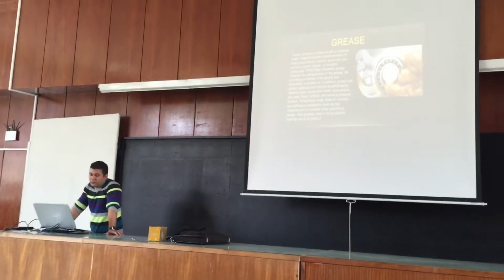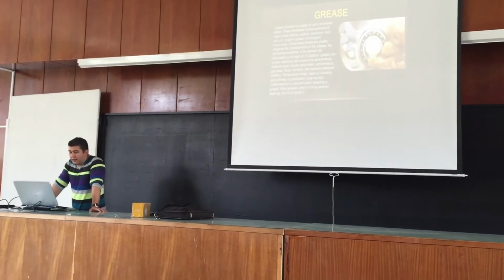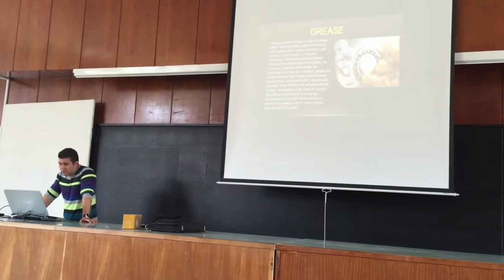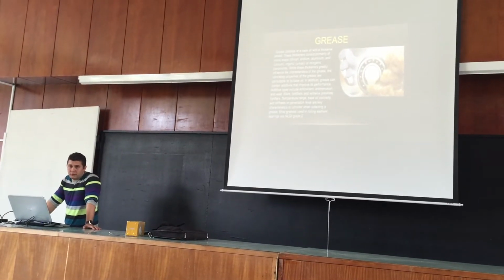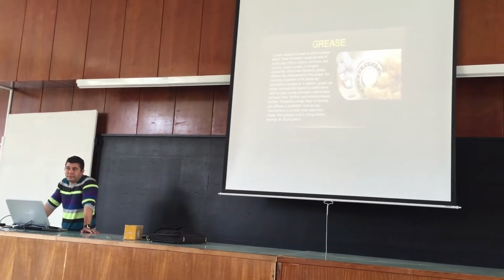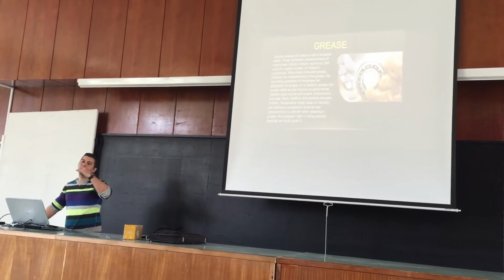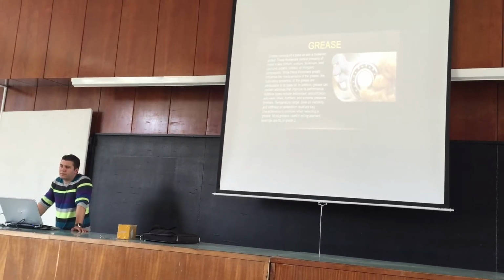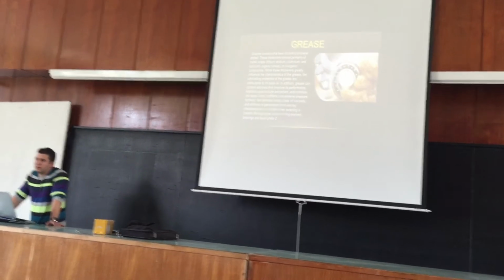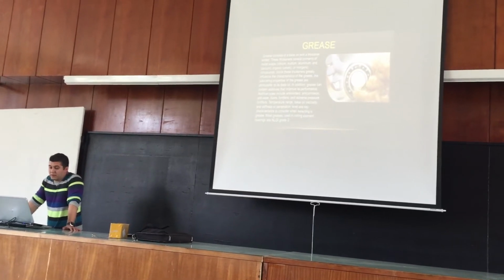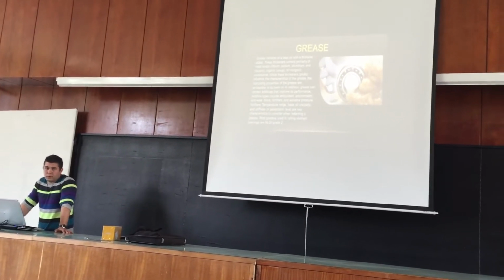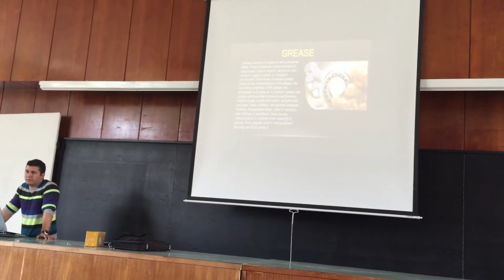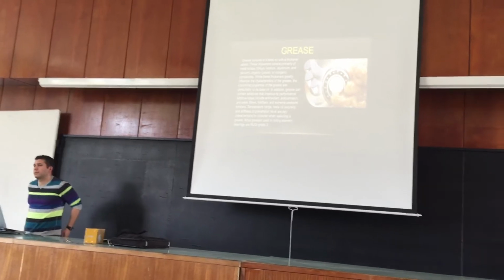Okay. And what do we use? Most greases used in rolling element bearings are NLGI grade 2. As I say, there are different grades, more thick or less thick. What is the difference in grades? Why do we have grade 1, grade 2, grade 3, grade 4? As I know, it's for different temperatures, different viscosity. Different viscosity. Yes. Okay, next.